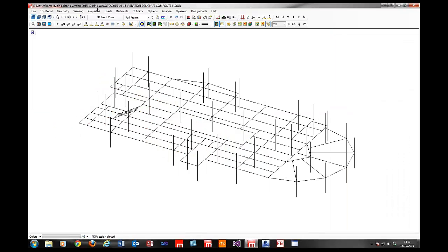So that's the setup of the finite element surface. The other thing the SCI P354 tells us is that end releases are generally, you can ignore those. So there's no end releases on this. And that's simply because the deck is continuous to start off with. So therefore, fully simply supported members don't really exist in reality to that effect. And at the level of movement that we're talking about in terms of vibrations, the assumption that it is fully fixed has been justified.